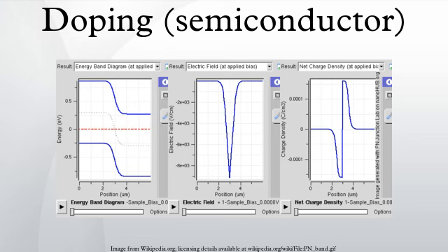The reaction conditions typically range from 600 to 800 degrees Celsius for the N-doping with group 6 elements, and the time is typically 6–12 hours depending on the temperature. Process: some dopants are added as the boule is grown, giving each wafer an almost uniform initial doping. To define circuit elements, selected areas, typically controlled by photolithography, are further doped by such processes as diffusion and ion implantation, the latter method being more popular in large production runs because of increased controllability.